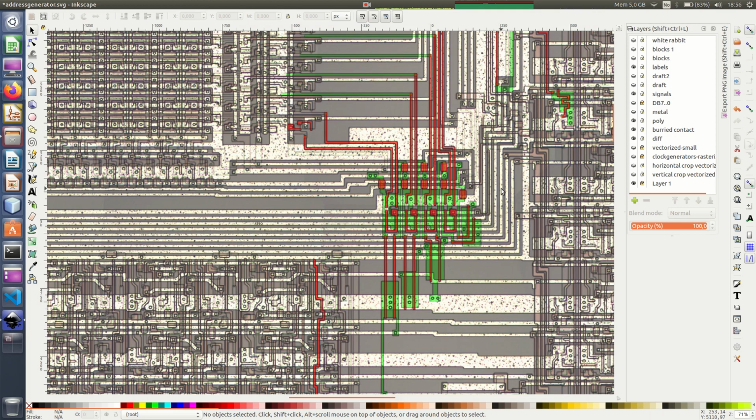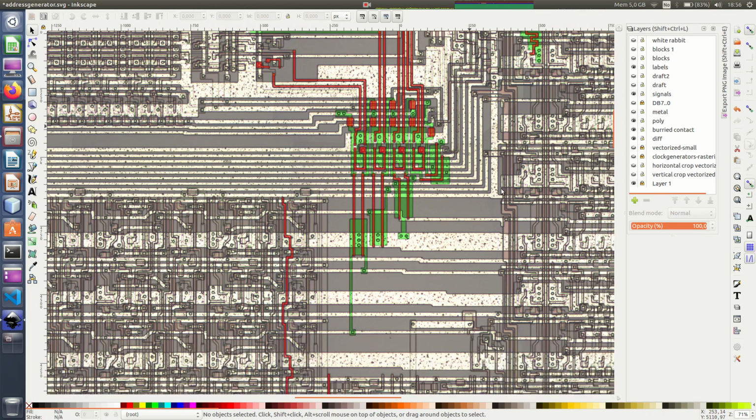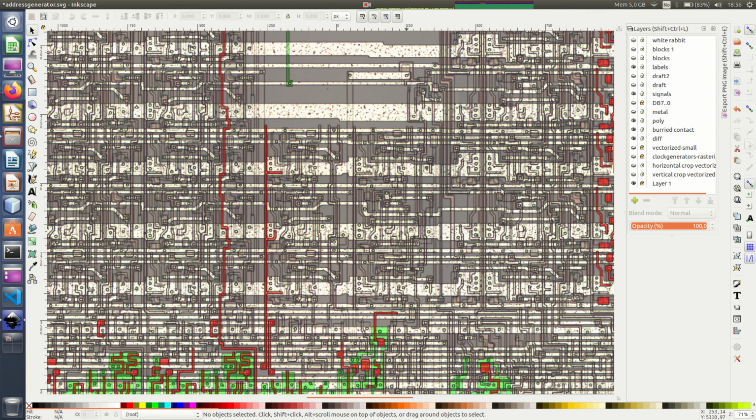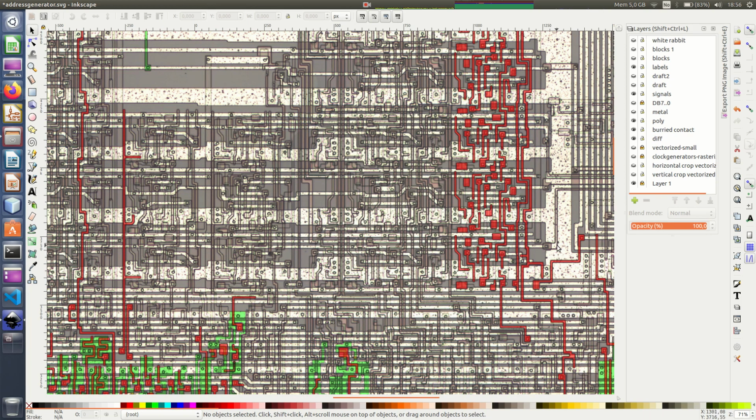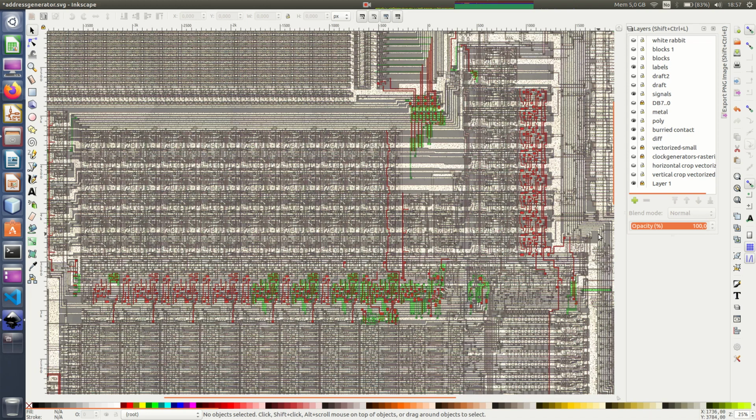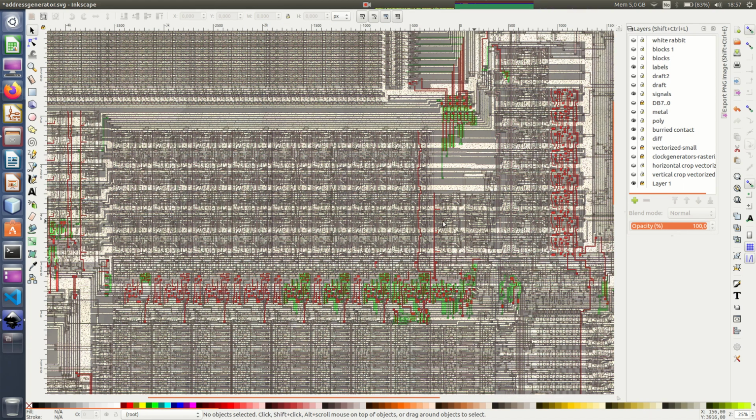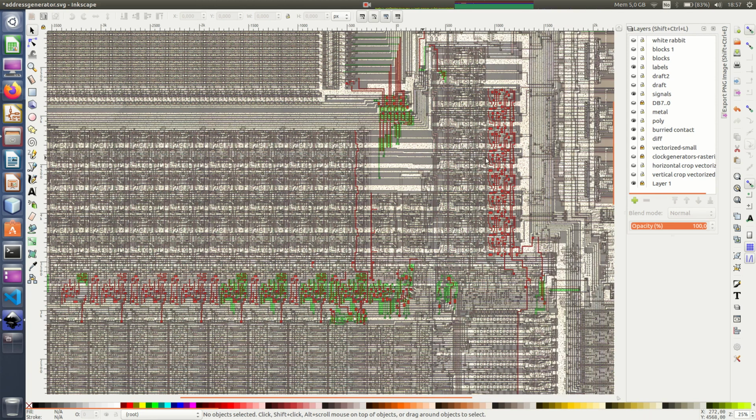But that's not enough. We need to slice them up in 8, right? So therefore you need a 3-bit counter, which I believe is down here. You can see there's an address line, this one. So that's the whole address. We have the upper bank selection, we have the character selection, which comes in here, and we have the counters to keep track of which slice of the character it's displaying.